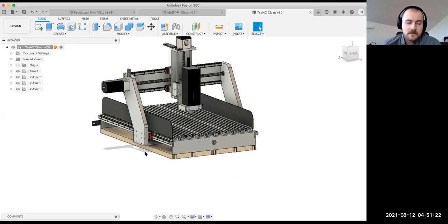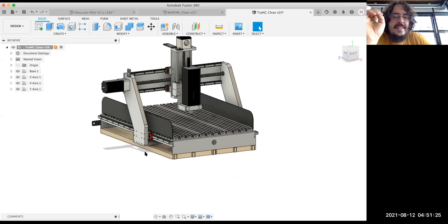1,500. Okay. Yeah. So guys, there is a problem, which is, of course, you can buy a Chinese CNC 6040 for around 800 euros here in Germany, shipping included. All right. So you ask why you would make such a machine, because this machine, guys, can cut aluminum much faster than the other machine, and it can achieve a precision that the other machine will never be able to reach. So we have more precision and faster speeds. The first thing I do in a CNC is I take the holder, the spindle, and I try to bend it by hand. If you do this in a CNC 6040, the bending is instantaneous. And here you need to put some force to bend it.